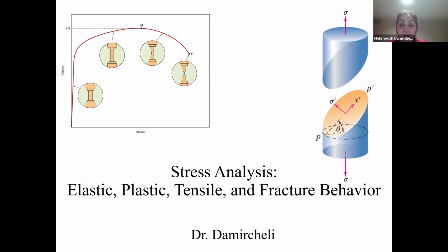What is the yield point, the properties of the yield point, the fracture point, and I will show how to determine modulus of elasticity or Young modulus, percent elongation or EL percent, modulus of resilience, modulus of toughness, ductility, and ultimate tensile strength directly from this curve.